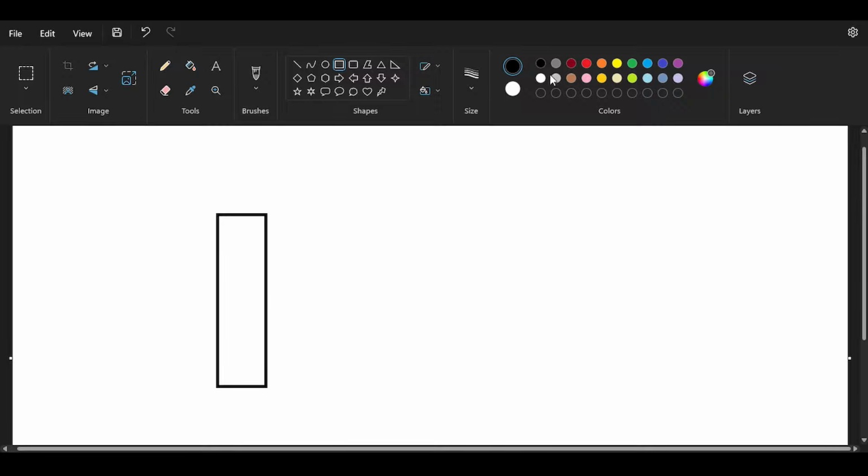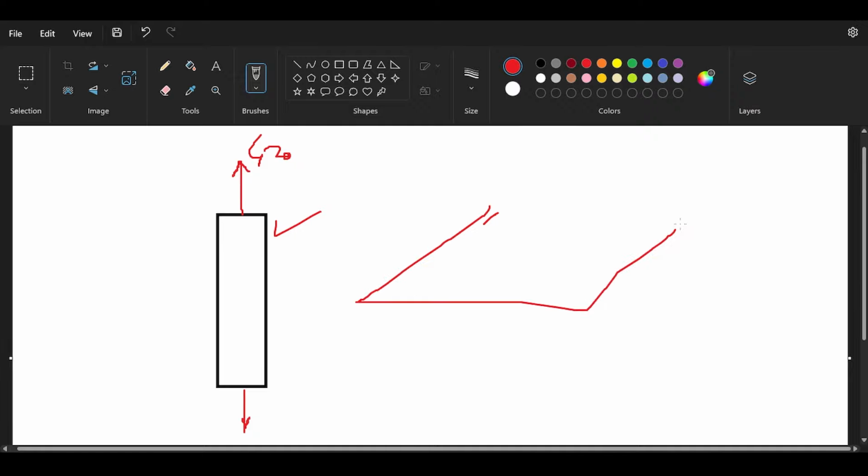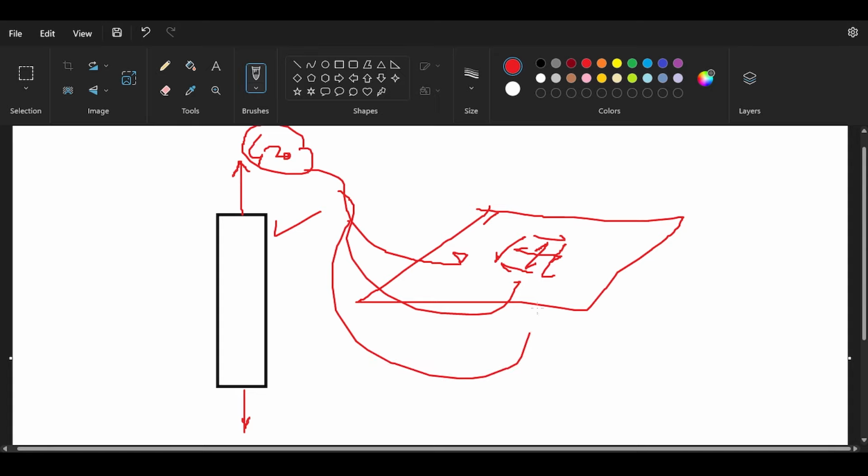If you have a steel bar and you say this steel bar has a yield strength of 420 megapascals, this is the one-dimensional yielding, meaning if you apply a stress in 1D of 420, then it will yield. Now, this perfectly works for members of linear nature, like beams and columns and whatnot. But in a plate, you know that there is a combination of stresses in the x-axis, stresses in the y-axis, stresses in the 1-2 axis, which is the shear axis, and all kinds of stresses in a plate. So suddenly, the 420 is to be shared with the x stress, with the y stress, and with the shear stress. And nothing shows it more than Mohr's circle.